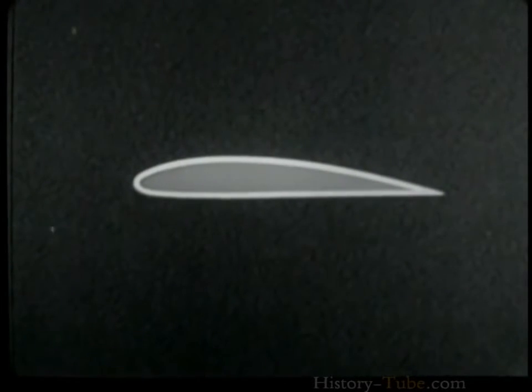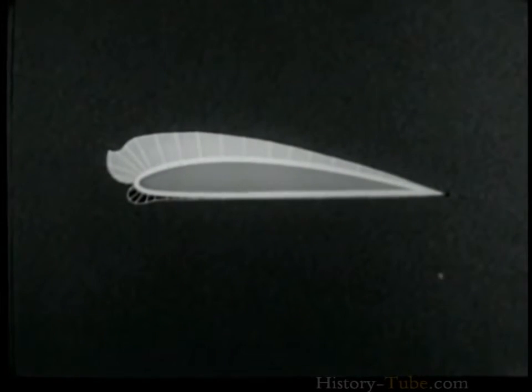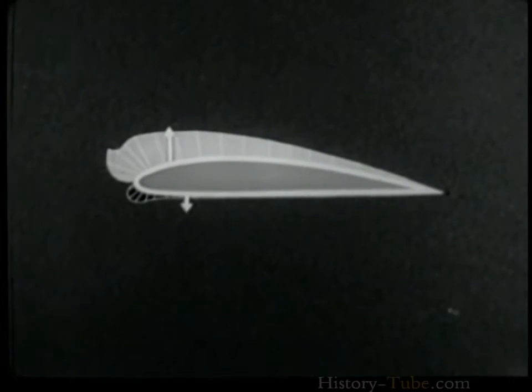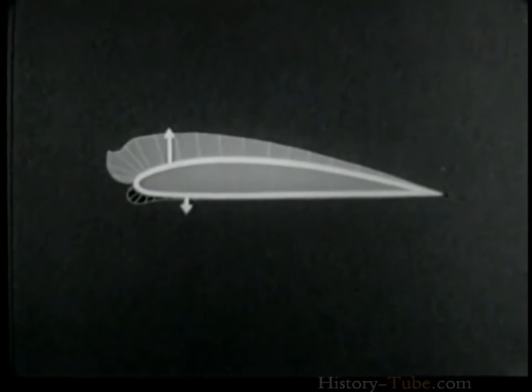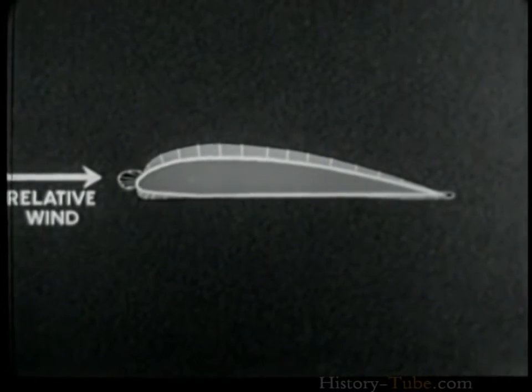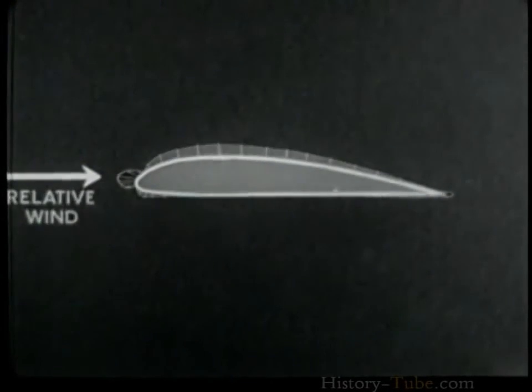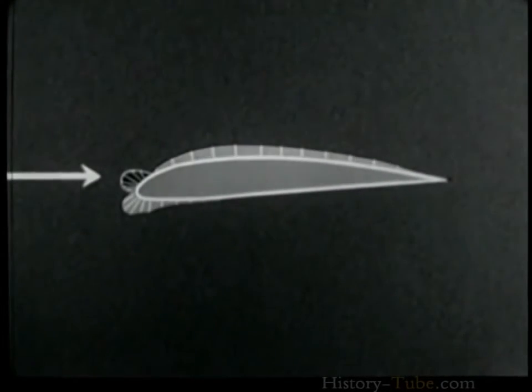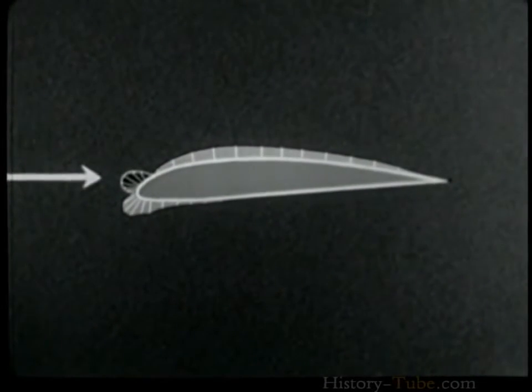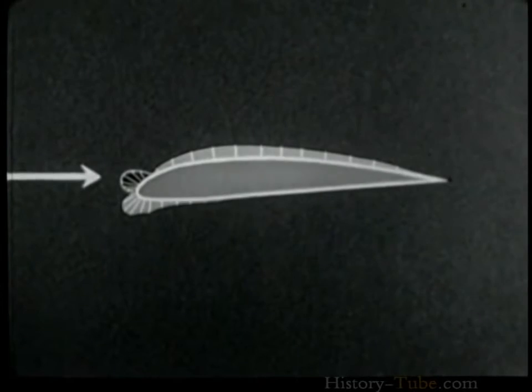An airfoil at rest in still air is at atmospheric pressure over its entire surface. It has been shown that airfoils derive their lift from the pressure differences acting upon their surfaces, the negative pressure difference upon the upper surface at normal angles of attack being the major component of the lift force. Now let us see what happens to pressure values and distribution at negative angles of attack. From 0 degrees, the angle is decreased to a slight negative value. The positive pressure bulb on the leading edge is practically unchanged.